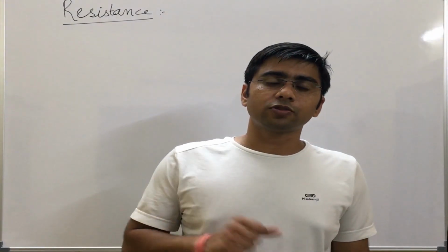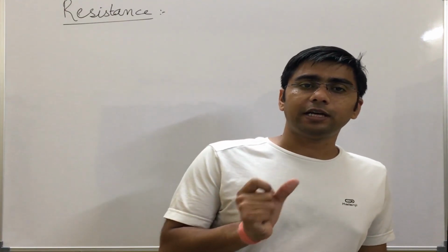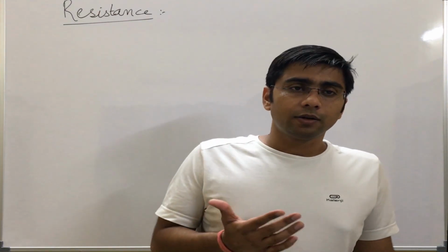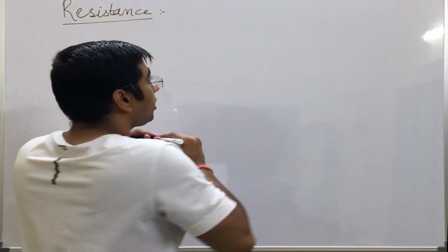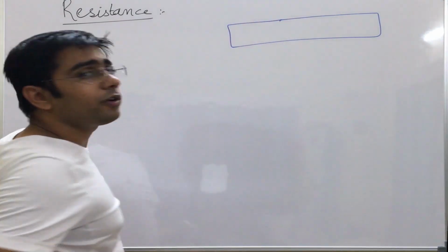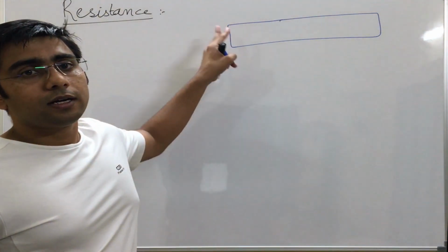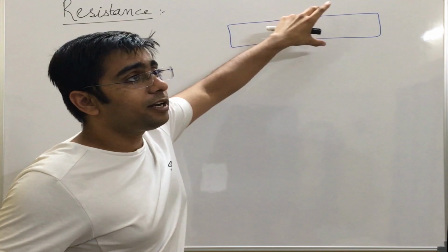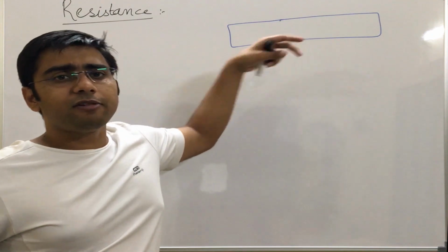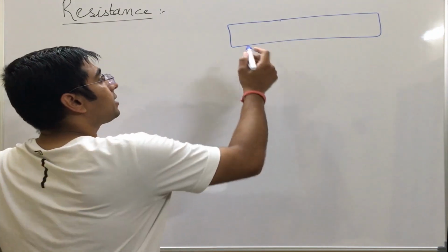Our next topic is resistance of conductors. But before going on to that topic, there was one little point left in the previous topic. Why do we need to make stranded conductors? If I make a totally solid conductor, say like this, what will happen? It will be very difficult for me to place this conductor because of its high weight and reduced flexibility. Due to lesser flexibility, it will be very difficult to string it over the poles. So that's why I make this conductor stranded.